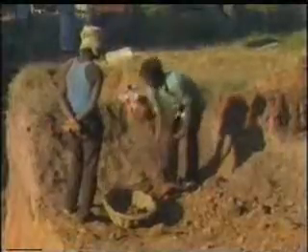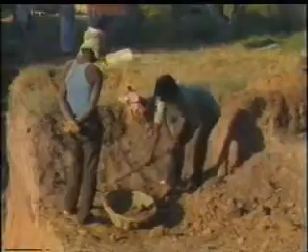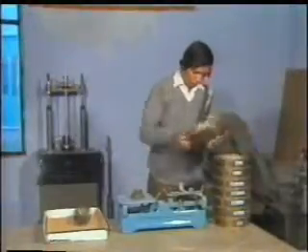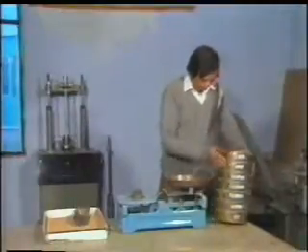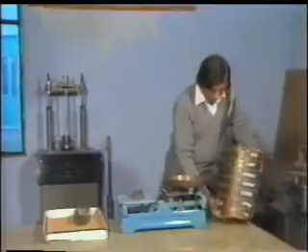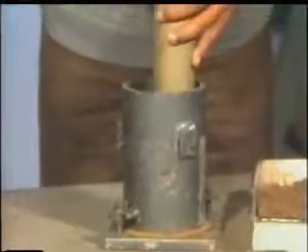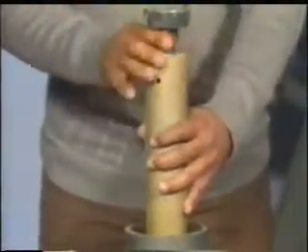Disturbed samples are enough where soil is to be used for construction purpose or when exact determination of properties is not required. They are also used for soil classification, moisture content determination, or to obtain compaction characteristics.